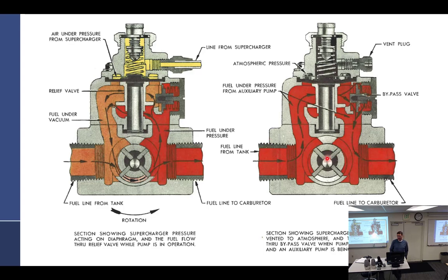Makes sense. The very second that the engine-driven pump exceeds the pressure of the boost pump, because this is the outlet right here, when this outlet pressure starts to increase over the boost pump, it'll come up into here and push this closed. And so then this takes over. So that's what happened over here. We started the pump going, and the output pressure was sensed back here, was greater than the boost pump, and closed this. So the boost pump could still be running, doesn't hurt anything. So close that. Okay, now we're in our closed loop system.